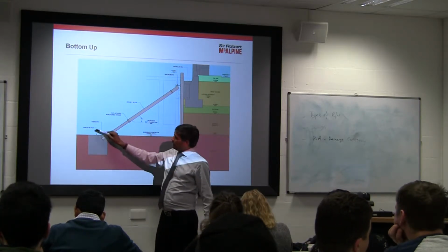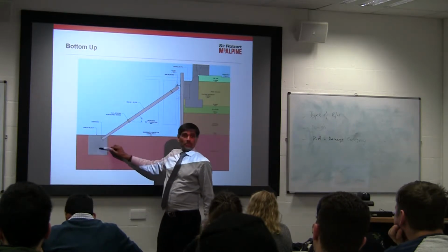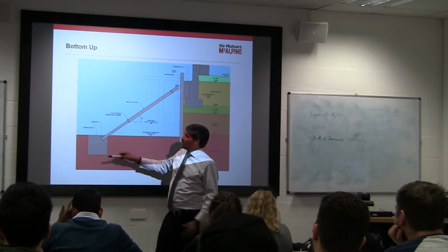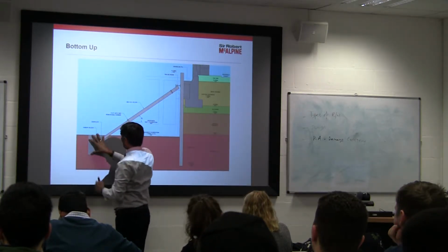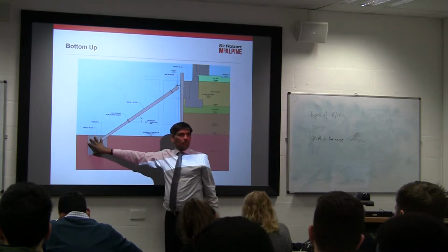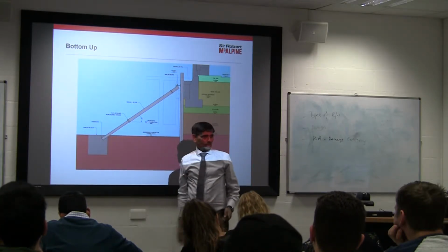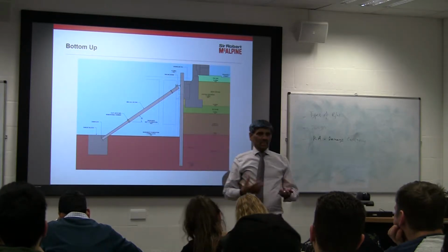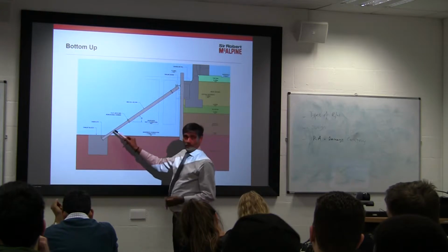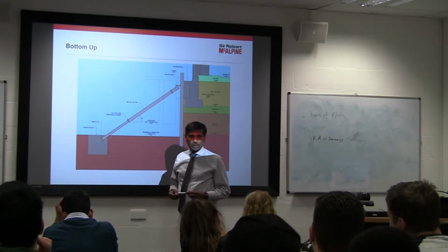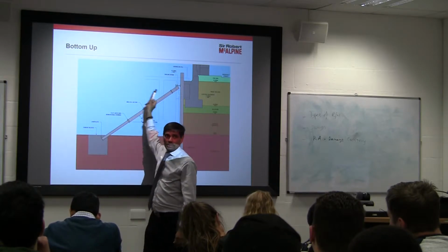So you have to create a local pocket from the ground level, at that level. Basically you create a trench here, because your ground level is here, you create that lump of concrete, and then as you dig down, you anchor it. So you need a thrust block to hold it. That's because we have got a raking prop. This is called a raking prop, because the prop is obviously raking. You may have a fly-through prop, then you don't need this one. So you go from one end to the other end.